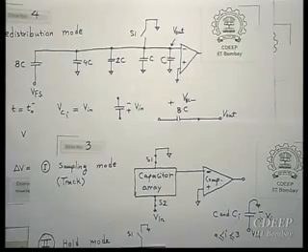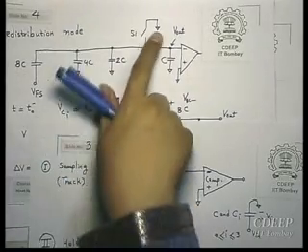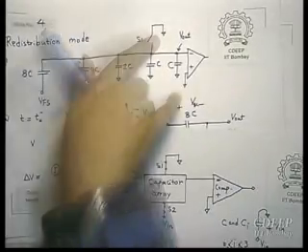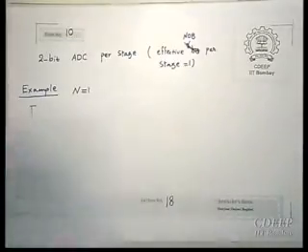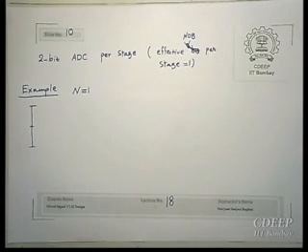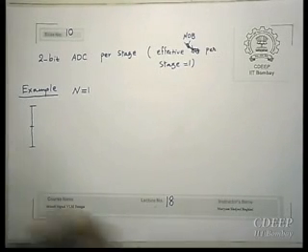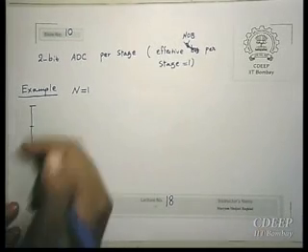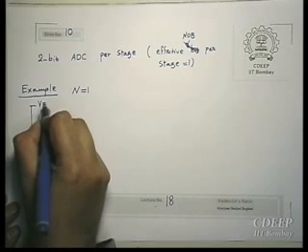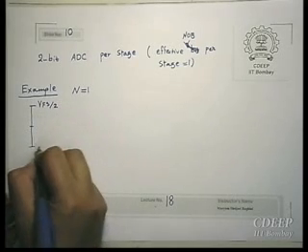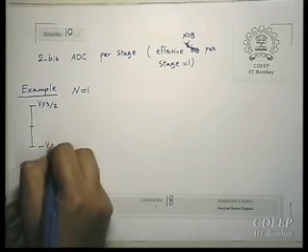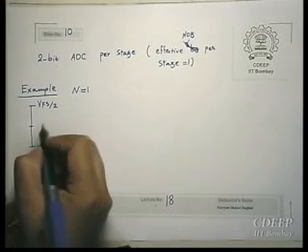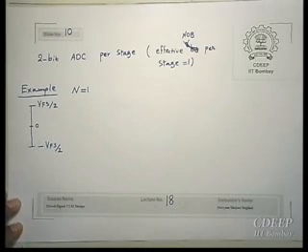Therefore, that V common mode doesn't have any impact. So just these two will get connected to V common mode. Okay. So here also again I am using ground level or the 0 level, because in the application note it is like that. So that is okay. So what I do is that instead of 0 and V full scale, I make it minus V full scale by 2, V full scale by 2 and 0. It's just the shift makes the reference level 0, middle reference, to be compatible with that.